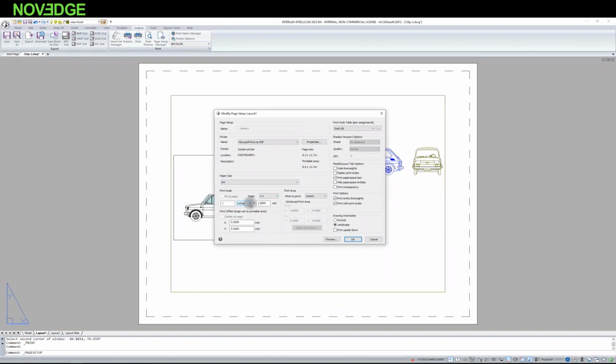I'm certainly also taking over the calculations to millimeters, but I'm defining the scale at this point to a scale of 1:1. That's because here in this sheet I'm actually defining the print sheet, which is exactly the sheet on which I'm printing at the scale of 1:1 in units like millimeters or inches if you prefer. And I'll print the sheet, which is everything that is on this sheet. The scale is 1:1. You can center it if you want.